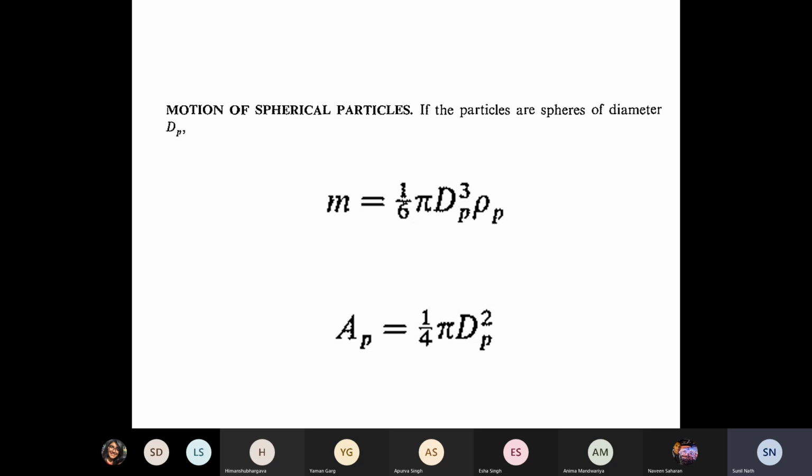Now what I would like you to do finally is, for the Stokes type of flow, the CD is given by a very well-known expression which you would have done in Bird-Stewart-Lightfoot, except that he expressed it in terms of f. But nonetheless, in that creeping flow, the CD is always inversely proportional to the Reynolds number. So can you remember that expression? Can anybody tell me what that expression was for very streamlined flow, or Re less than 1 in our case?